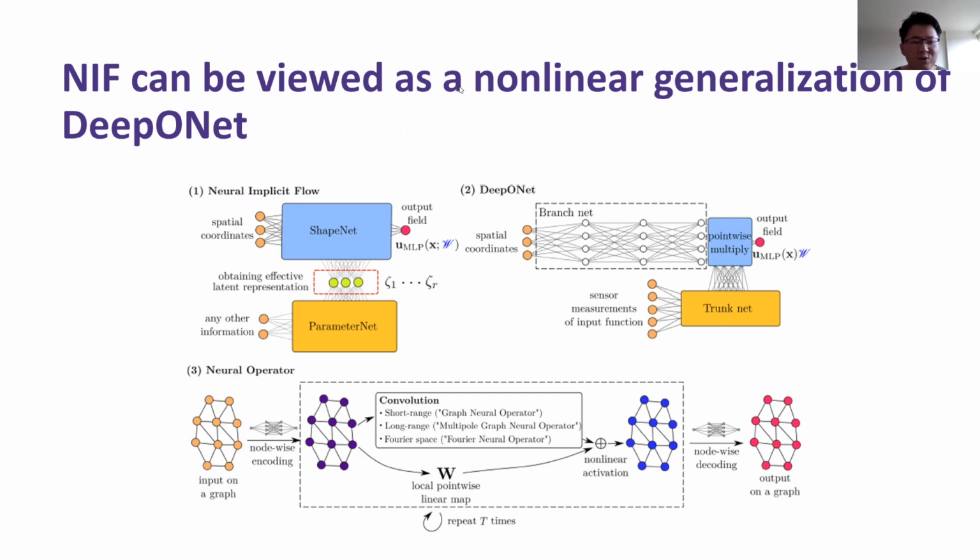If you're trying to use this temperature to predict the chaotic turbulent velocity away from the wall, I would run away from this. It's probably not going to work at all. But if these 5 temperatures are going to predict, let's say, the time-averaged mean temperature profile near the wall, maybe just 10 cells above, then I would say maybe it's a good shot. So not too far from the trained boundary conditions.